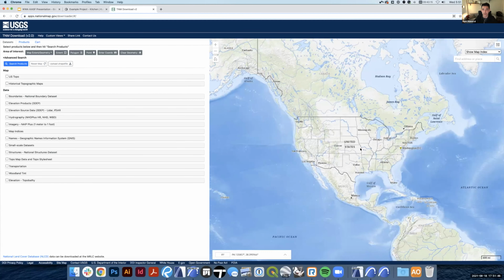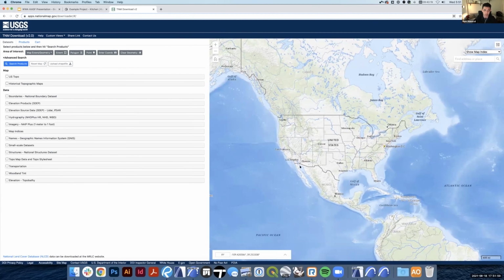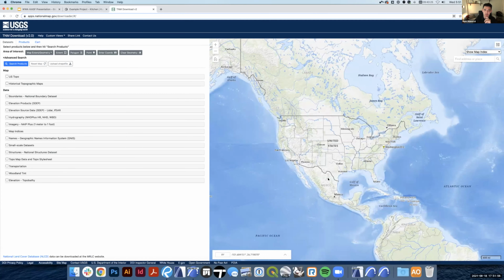You can type in your project address and it'll give you a height map, which we then take into a program called QGIS, which analyzes that and turns that into contour lines. However, in Twinmotion, you can also just directly import height maps to do the same kind of landscape sculpting that I believe Sam was talking about. And I think that'll work for some situations where you have a lot of site up close, but if you wanted to get distant mountains way in the back there,